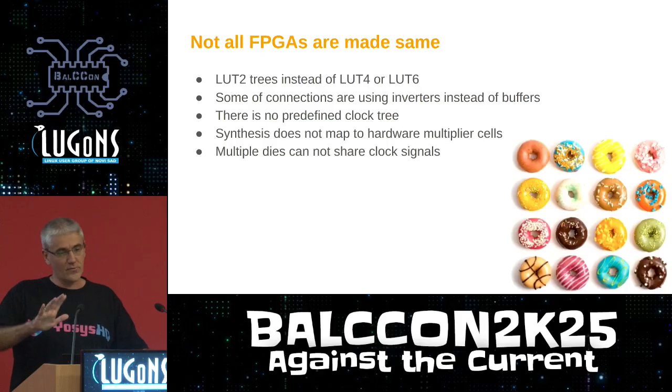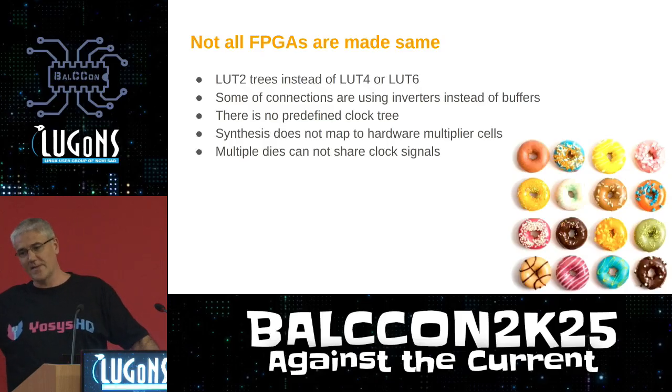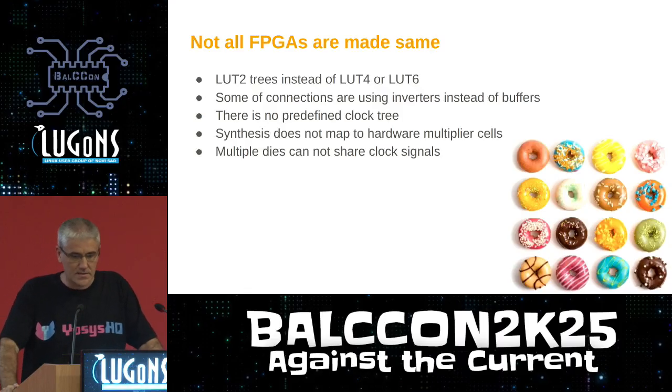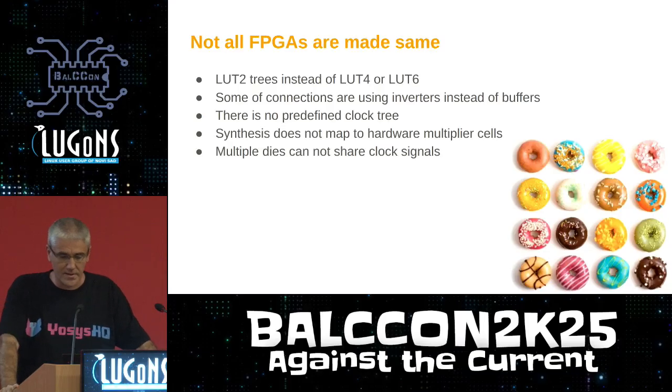And actually it also depended on position, because depending on how long you are jumping into another tile, you may or may not go through a number of inverters. So that is something that's quite different from other FPGAs, but also due to the same reason, there is no predefined clock tree, and because there is no predefined clock tree, that means that you need to create your own clock tree, and creating a good clock tree is actually not a simple job.